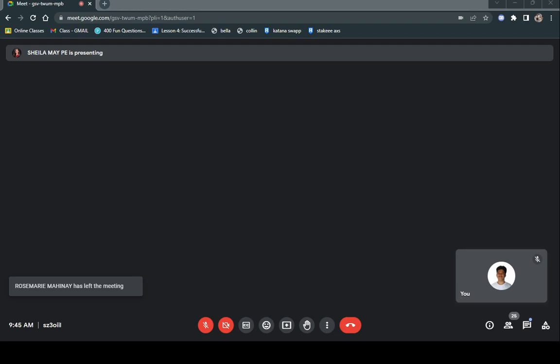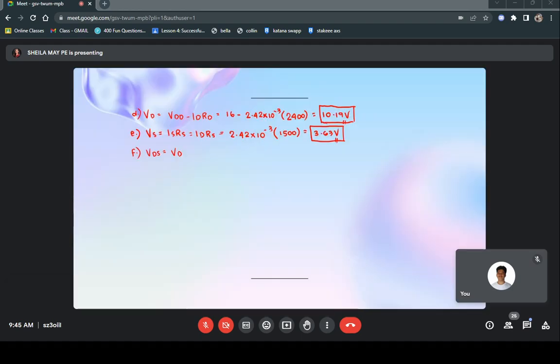Okay, lastly, we need to find our VDS. VDS has a formula of VDD minus ID times RD plus RS.